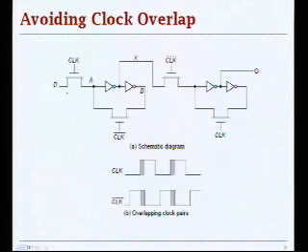What we have is also a master-slave configuration. And what we do here is a couple of things. First, we want to reduce the clock load. In order to reduce the clock load, we implement this pass gate function using only one transistor. We don't really want to do the full transmission gate. That's expensive in terms of power. And we also implement this approach of breaking the feedback loop, injecting the state, and then keeping it.